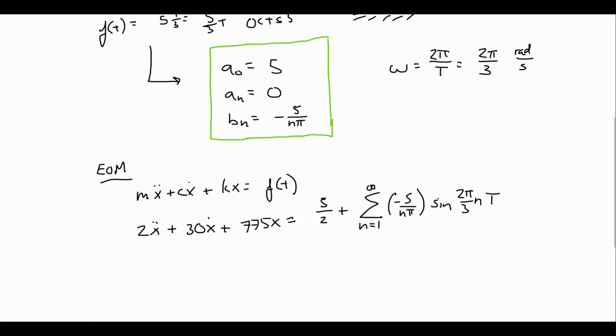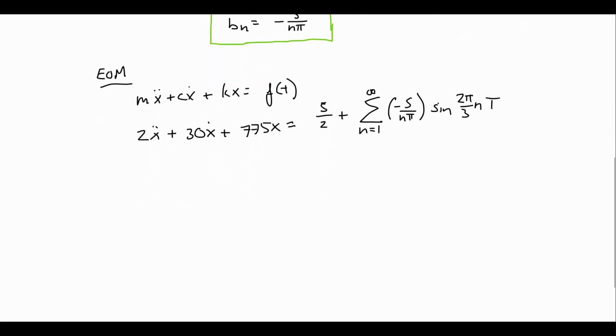With the equation of motion written down, now we can go to our identify step and we can look at our equation of motion and see what we have. Looking at the left-hand side, 1 degree of freedom. It is linear. It is damped. We're going to see in a moment what kind of damping we have. And it has to be underdamped if we want to be able to use the homogeneous solution like we have been. But we're going to figure out what the damping is. And if we look at the right-hand side, now that it's expanded, it is this general forcing.